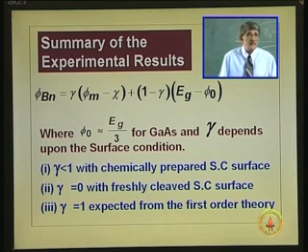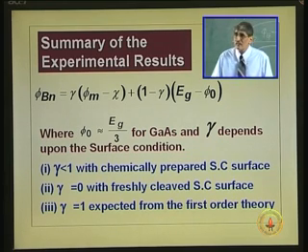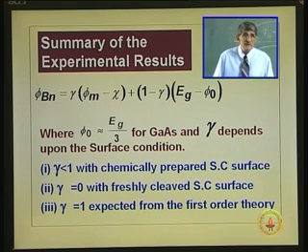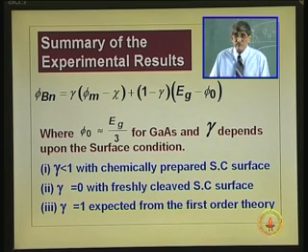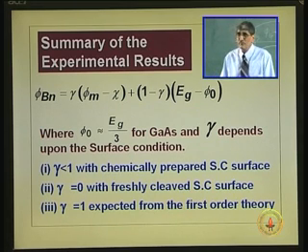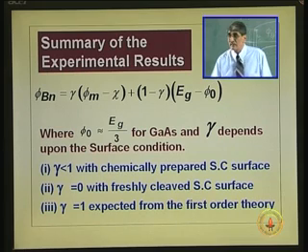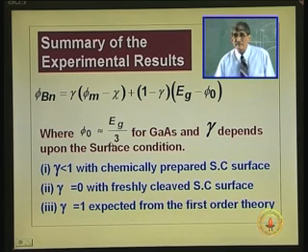Once you fix a semiconductor, the E g minus phi naught is actually a particular level within the forbidden gap. That turns out to be for E g by 3 for gallium arsenide and silicon. For indium phosphide it is slightly different, it makes your life much more miserable for making MESFETs there, that we will see later on. Today we will focus on gallium arsenide and silicon, where this is E g by 3. Okay.